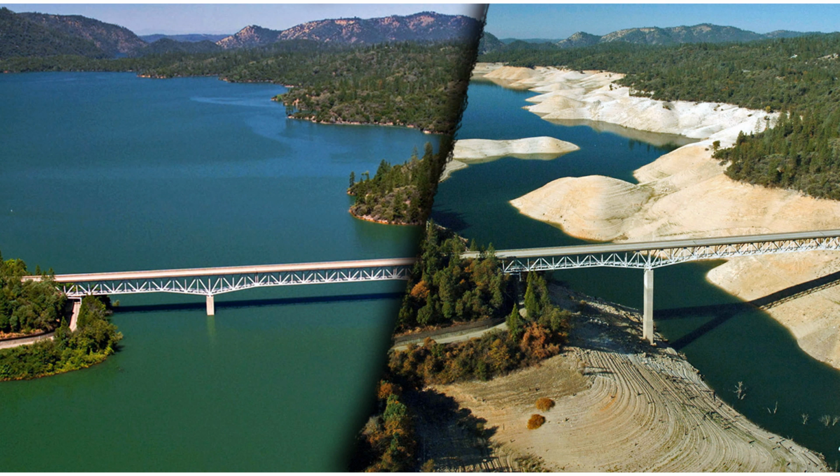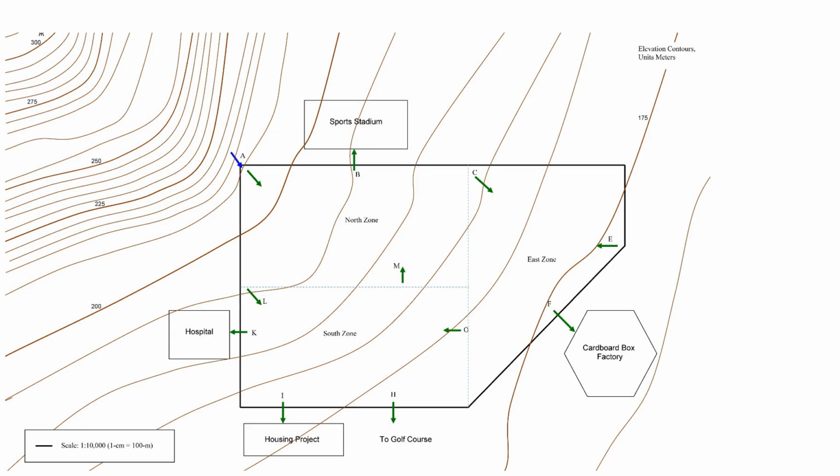So when we're sizing inlets for storm drains, or when we're sizing storm sewers, we have to ask ourselves not what are the climate conditions now, but what are maybe the climate conditions 50 or 100 years in the future likely to be. Because when you put a pipe in the ground and then put a road on top of it, you don't want to dig the pipe up when weather conditions are changing. So you have to think into the future.